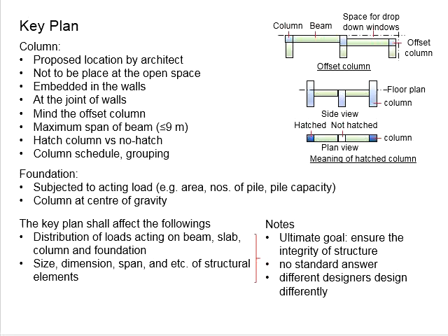In the case that you don't have sufficient soil bearing capacity, that means deep foundations will be required. This is where you need pile foundations, and there will be pile caps to group the piles together and to equally distribute the loads from the building into the piles and then to the hard strata below the ground.